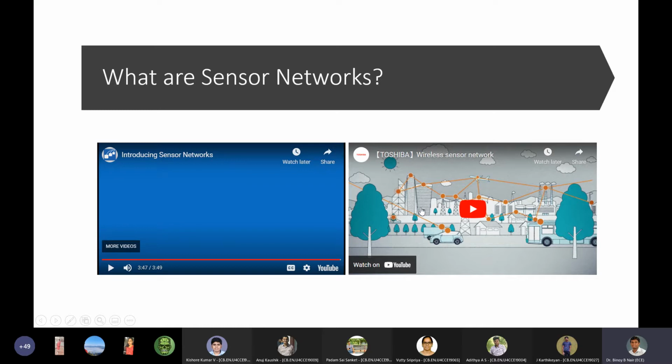So ideally, whenever you are making some kind of analog measurement, it is a good idea to have a short length of wire to the processing unit. I don't know if that answers the question. EMI, electromagnetic interference, is a major issue. So you quickly convert it into digital as much as possible. Have a short run of cable, put it into a microcontroller, and once it is digital, it is difficult to corrupt. So that's how it works.